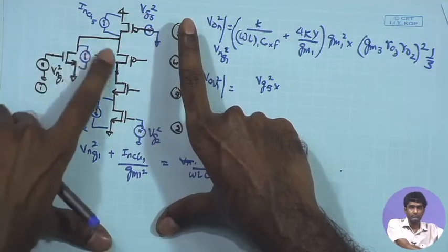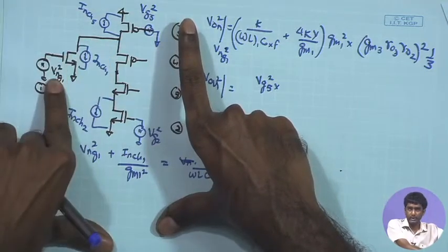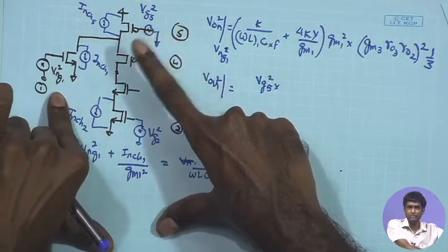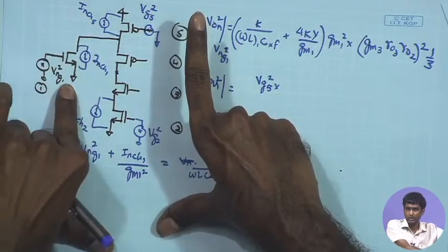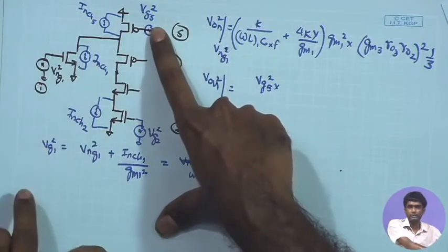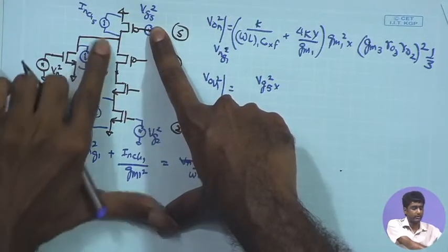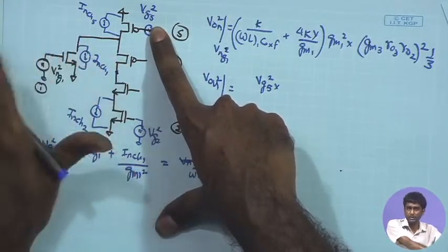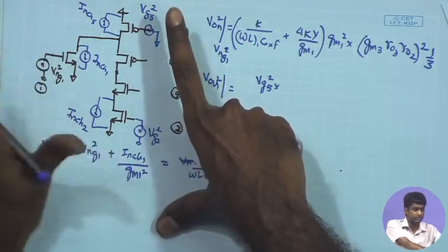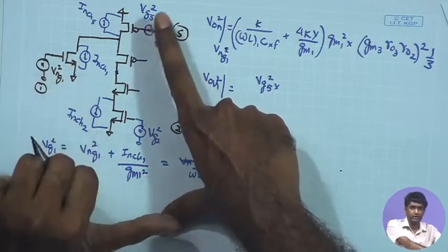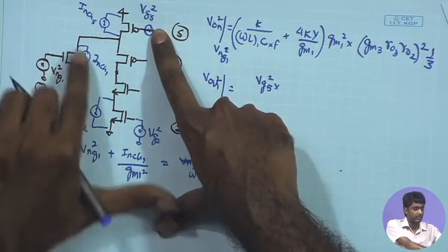Therefore, this will represent a stacked NMOS which is having an impedance of GM-RO square. It will not be just RO, it will be GM-RO square now. Therefore, while considering the effect of this VG5, I will ignore this branch, just like we did in the common mode feedback analysis. That distinction you should keep in mind.